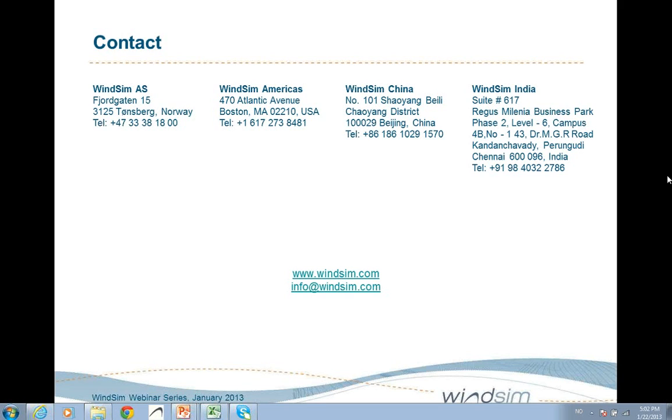Then there is a question how to obtain terrain data, for example, for Singapore. Here's the same. You would go into WindSim Express, and then you would specify where your turbine should be placed in your coordinate system. And then we will download the data automatically for Singapore. As these are worldwide data sets, you will also get the data for Singapore.